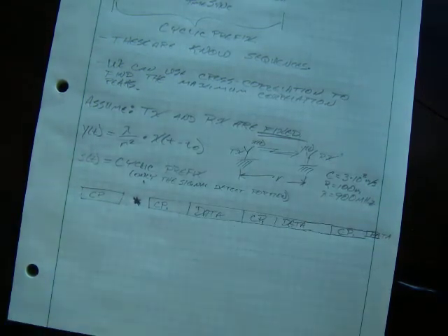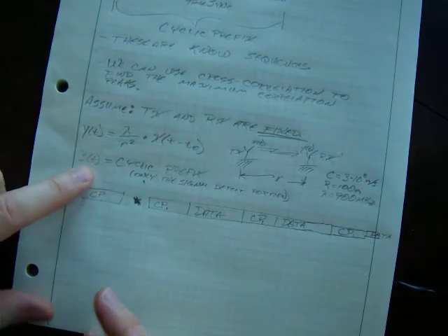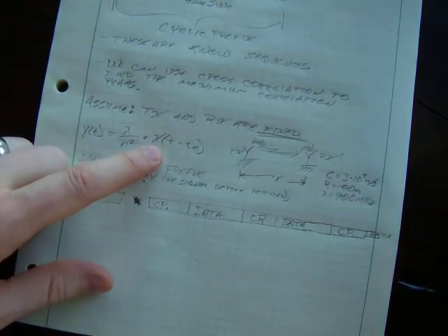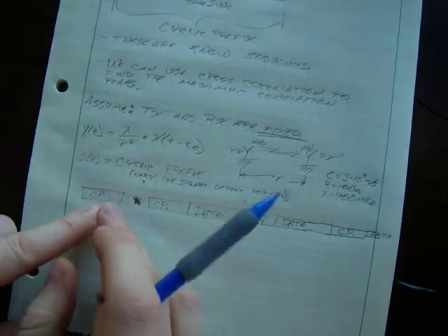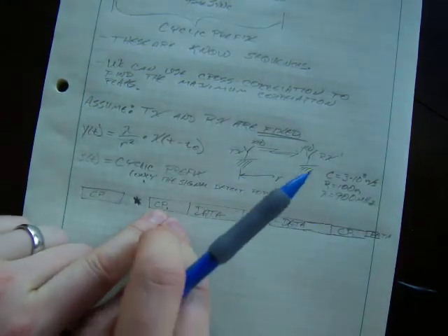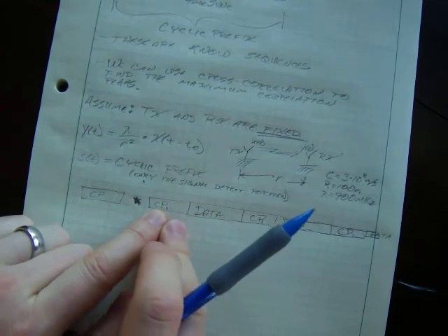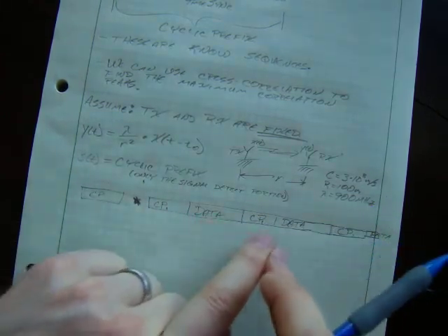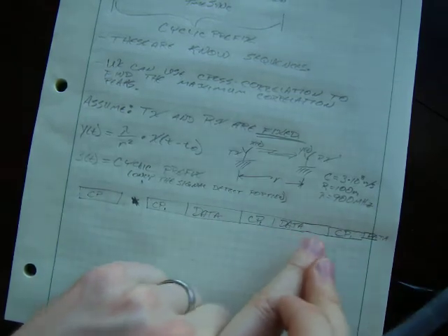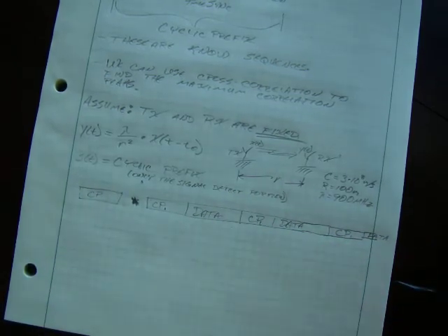They're going to be different because this one is the ideal version, and this one's the one that's actually getting transmitted out of the antenna. So we're going to do a correlation between the cyclic prefix and the data that we receive, knowing that the received data is going to be some form of the cyclic prefix followed by data, followed by the cyclic prefix, followed by data, cyclic prefix, data. And it just continues on.